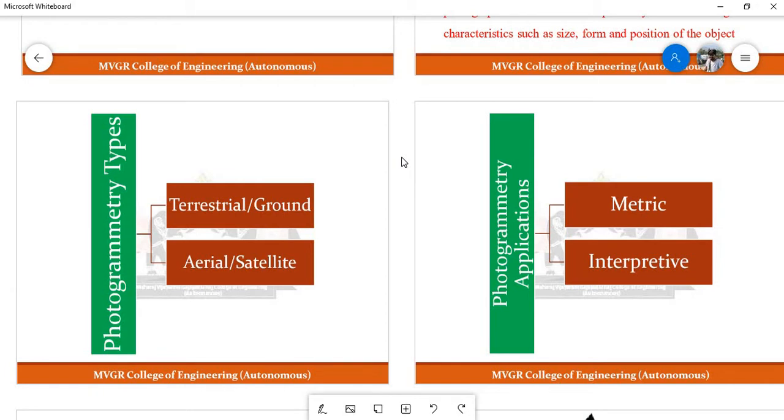Aerial or satellite photogrammetry means obviously with the help of aircraft or satellites we will take photographs. That type of photogrammetry is called aerial or satellite photogrammetry. And obviously the axis of the camera will be vertical, so the photographs will be somewhat vertical photographs from aerial or satellite. The axis of the camera in terrestrial or ground photogrammetry is horizontal.